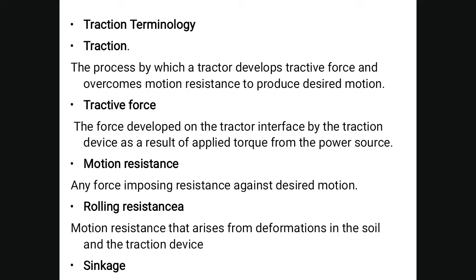Now the traction terminology. Traction is the process by which a tractor develops a tractive force and overcomes the motion resistance to produce desired motion. Tractive force is the force developed at the tractor interface by the traction device as a result of applied torque from the power source. Motion resistance is any force imposing resistance against desired motion. Rolling resistance is the motion resistance that arises from the deformation of the soil and the traction device.